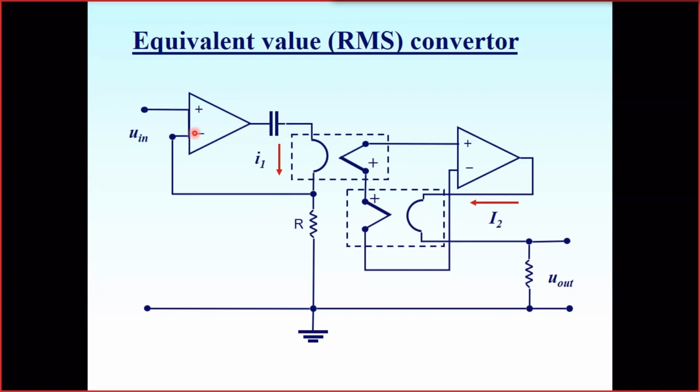Actually, this is an example of a voltage to current converter using an op-amp. The feedback here is used so that we apply a certain voltage here, and then the op-amp increases the output current till the voltage drop over the resistor R is equal to the input voltage. So it converts the input voltage into a current equal to the input voltage divided by R. We don't use just a resistor, because the resistance may depend much on temperature.